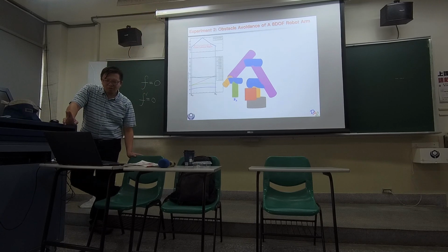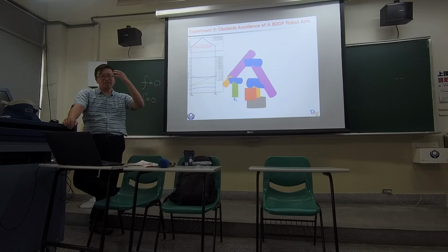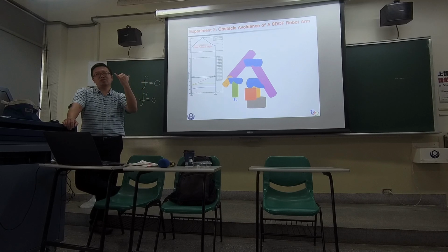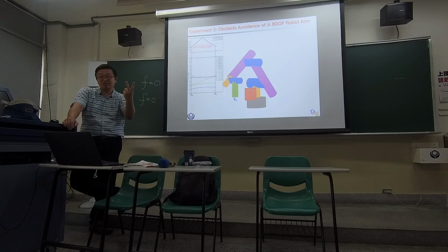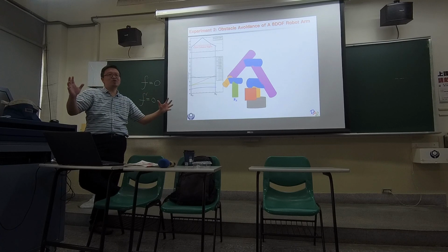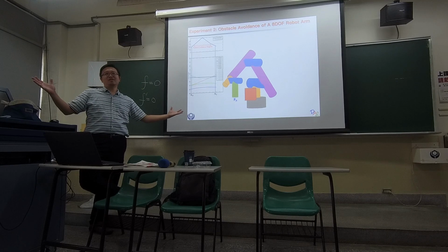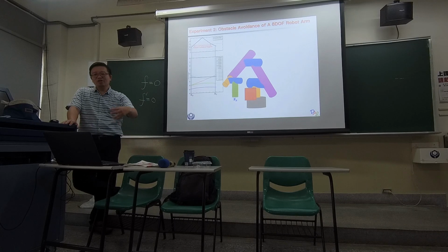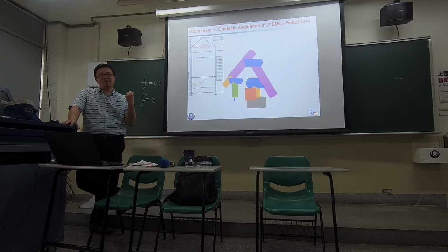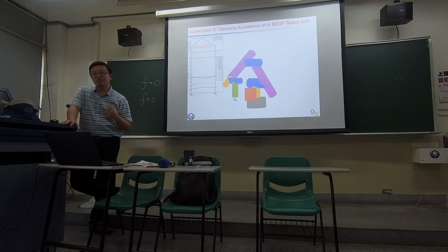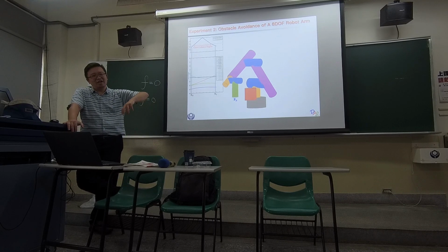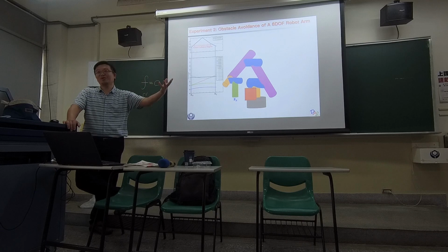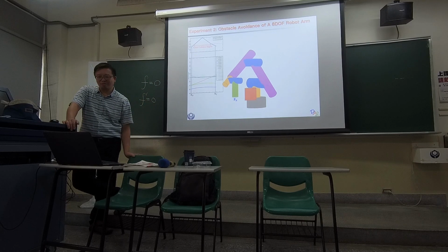But when they design this, as you can see, you have a greater degree of freedom. Now you have 8. You only need 6 degrees of freedom. So you have 2 extra degrees of freedom. So your possible solutions become infinite. You have an infinite number of solutions for inverse kinematics. So usually for this kind of redundant degree of freedom robot, finding the possible configuration is more troublesome than for a 6 degree of freedom robot.